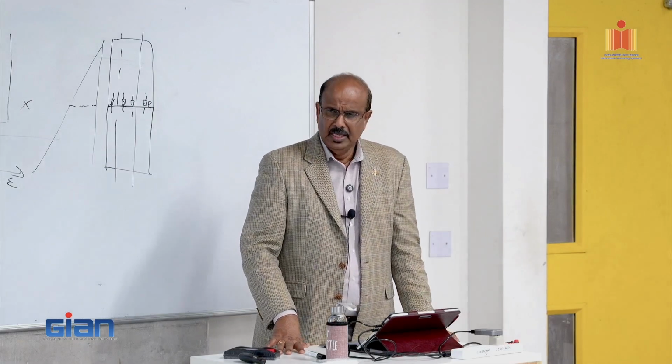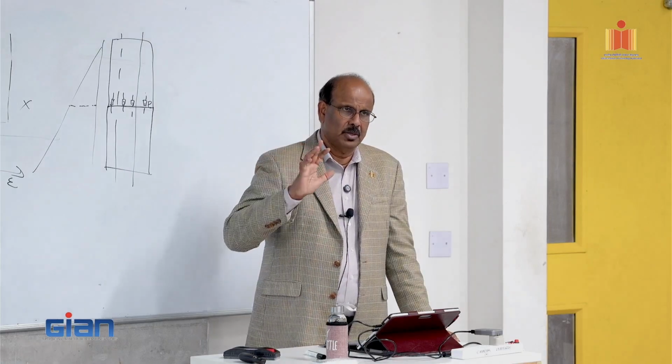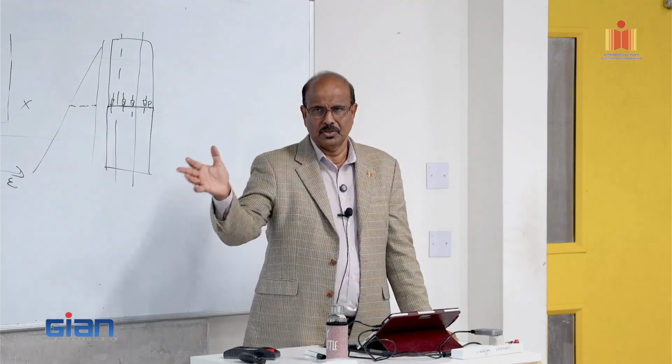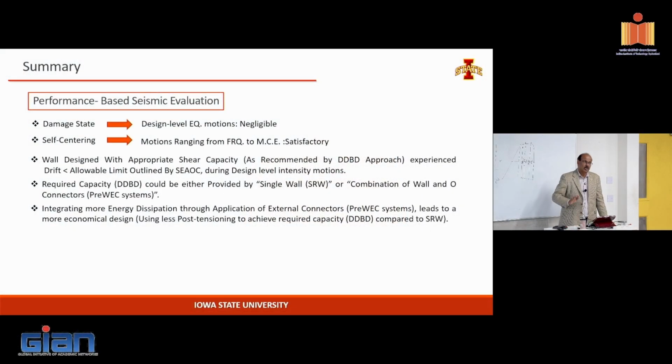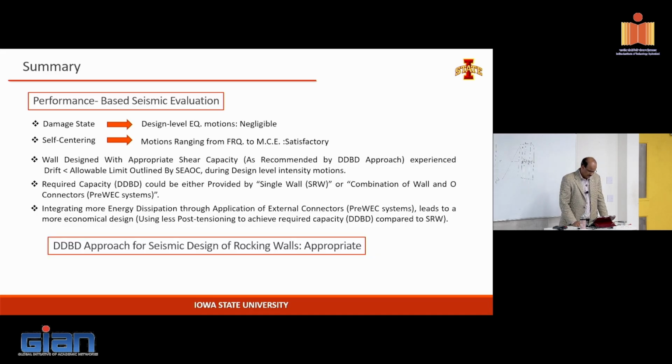So you don't have to come back to the original position after the peak displacement. The shaking that goes through back and forth eventually brings the structure down. We made some guidance that you don't put too much damping, because then obviously it will not recenter. So we can tackle that fairly adequately. In terms of meeting the performance criteria, for the most part, the structures met their expectations. There are some anomalies that you've seen, more so with the single rocking, and we made some recommendation as to how that should be tackled.